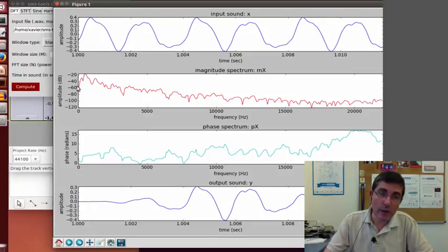Here the signal only reaches 0.4, so that corresponds to -20 decibels, and it goes down to -120. And the phase, we are plotting it using the unwrapping function. So instead of limiting the phase from 0 to 2 pi, we let it unwrap so that we see a much smoother shape, and that's going to be quite useful.